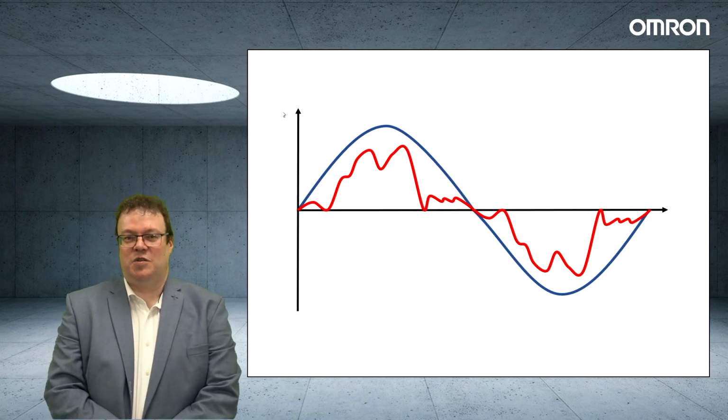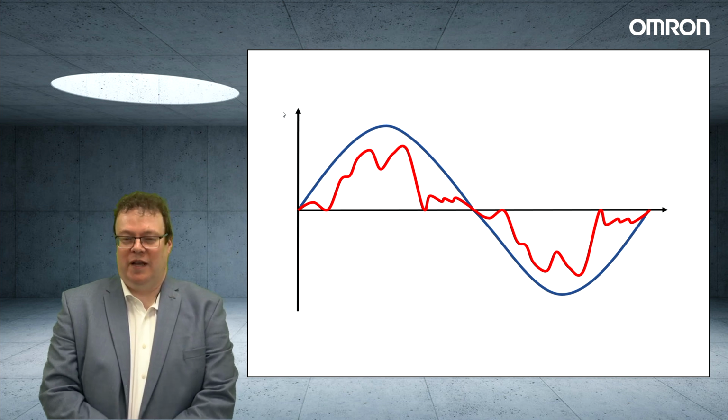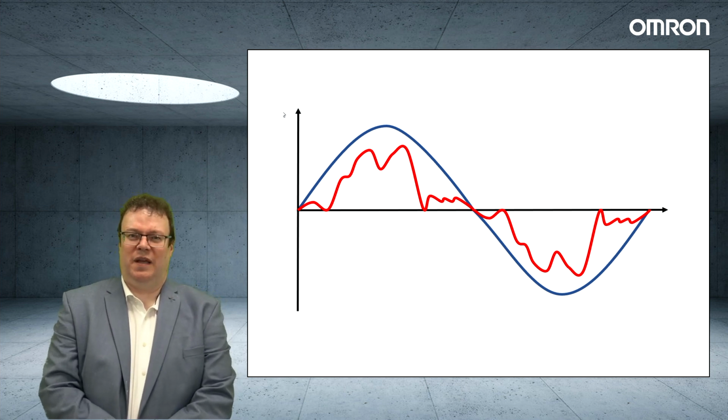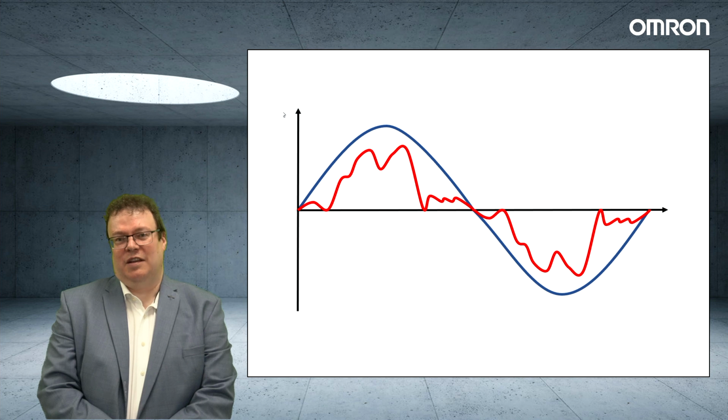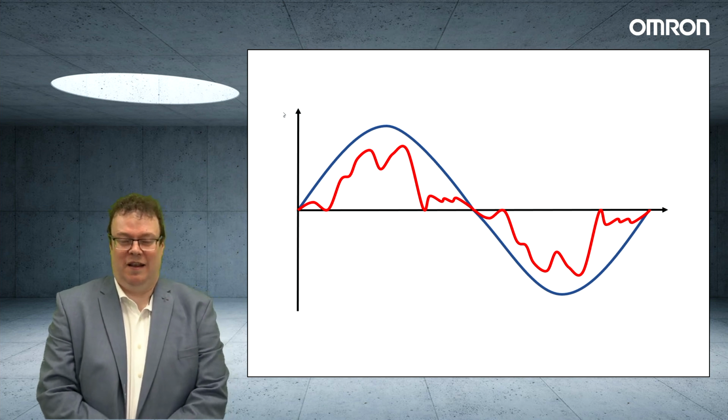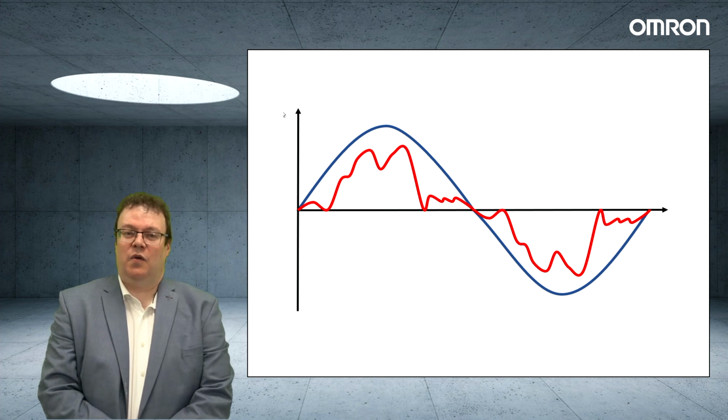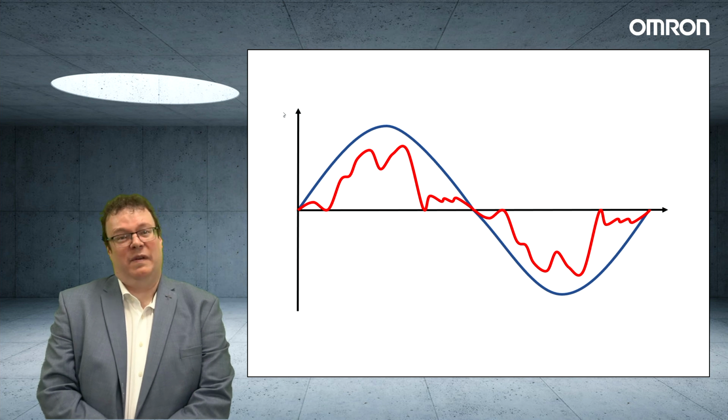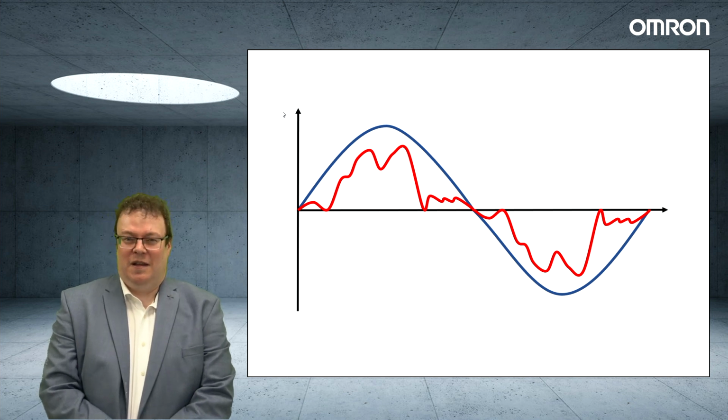We've also discussed in a short tech talk how pulse width modulation can cause a phenomenon called EMC and an issue with harmonic distortion. This is essentially where, because we have our nonlinear load switching very quickly, we can create a high frequency noise which basically rides on the carrier wave and can go back onto the main circuit that the drive is attached to, causing issues with other machines, comms, computer equipment, etc.